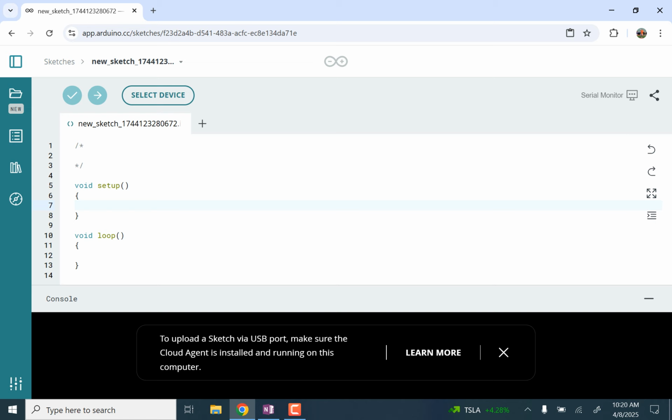And so the way you do that is through this function called pinMode. That's an Arduino function. pinMode takes 2 arguments. First, you tell it what pin you're talking about. We want 8, or if instead of 8 you use 6 or 7 or something else, put in the pin that you want to define. And then in all uppercase, we want to put OUTPUT. It's an output. We want to make that an output pin.